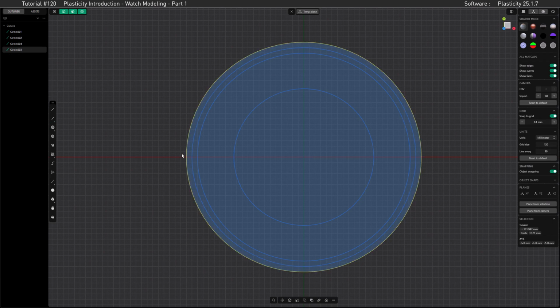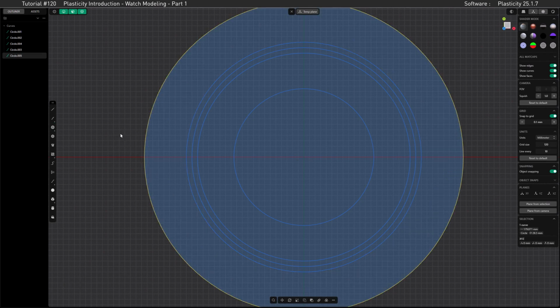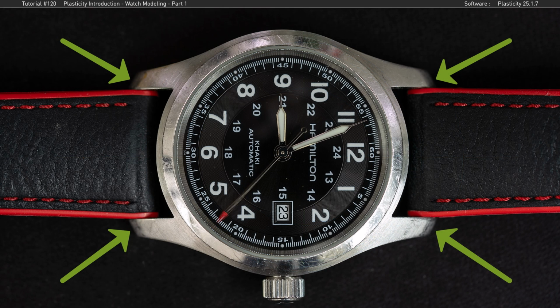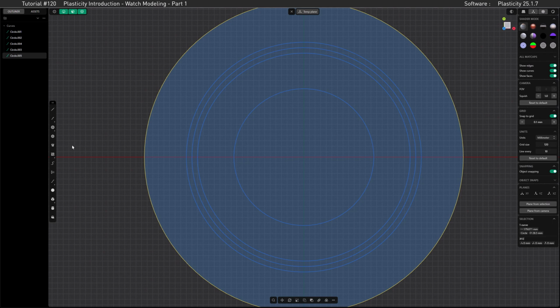Here we go. The last circle is the outer radius of the watch, so rather big. Hit Tab and then 57. Alright, those are all circles for now. Let's change the shape to a rectangle to get those standoffs working that hold the wristband. If you hold down the mouse longer on the rectangle, we can see more options, and we want to go with the center rectangle here.